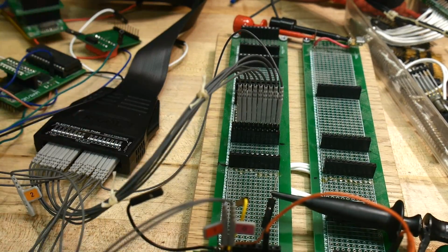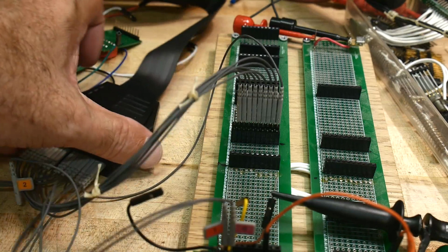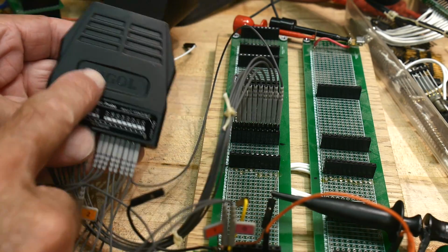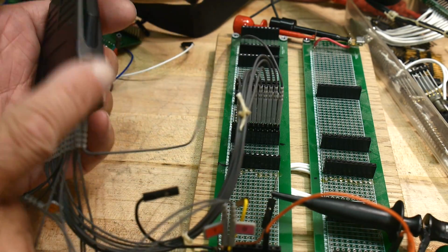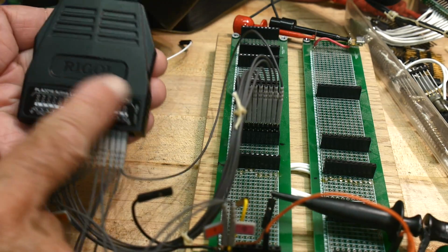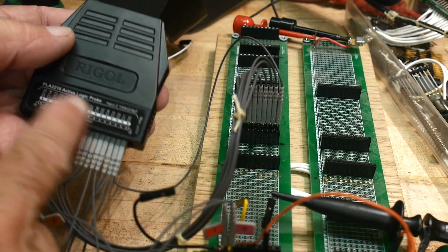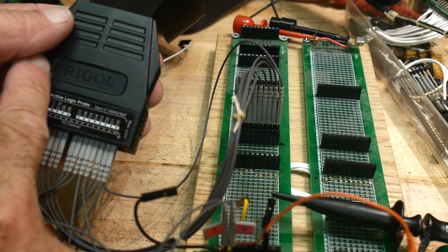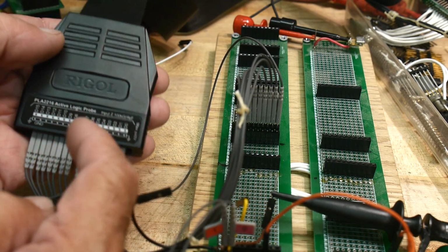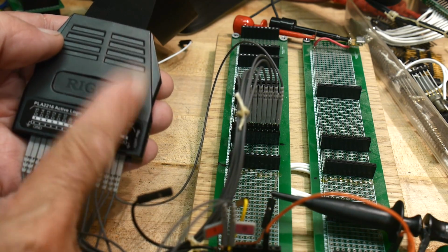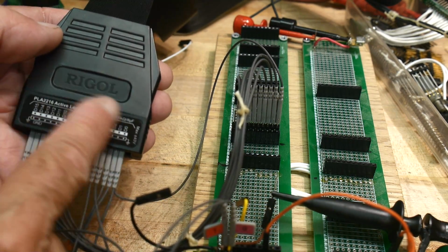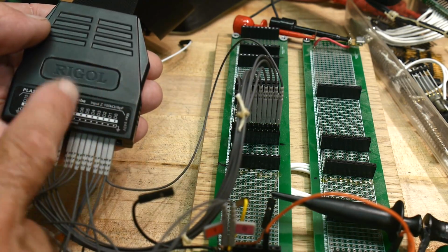So let's go ahead and hook up the logic analyzer. Now, people were confused about this cable. I said it was $300, but there's lots of circuitry inside this thing. I'm feeling it right now. This thing gets quite warm. There's actually 16 comparators in here. So when you pass a threshold, it'll fire, and you can program the threshold to different values, so it's quite clever.